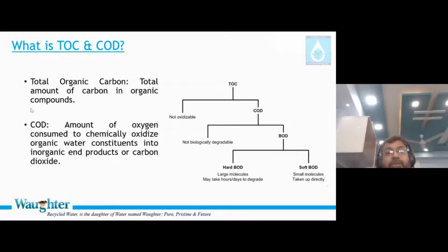So sometimes TOC and COD separately indicate to you, okay, this is permanent pollution. You can't do anything with that. This is the way you have to understand. Yes, sir, you have come to a COD level which is very, very low, but still the TOC level is this. Something you would have heard in the newspaper or on various channels and these kinds of media: a term came about called microplastics, microgels and microplastics. A lot of microplastic is available in the sea, and fish are eating the microplastic, and it is a hazard, right? Why? Because that is an indicator of TOC, but not COD. It's not oxidizable at all.